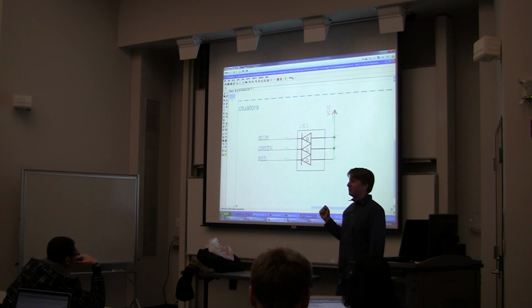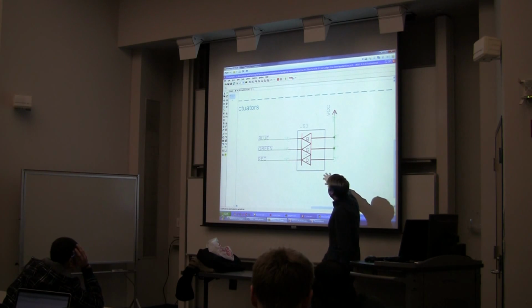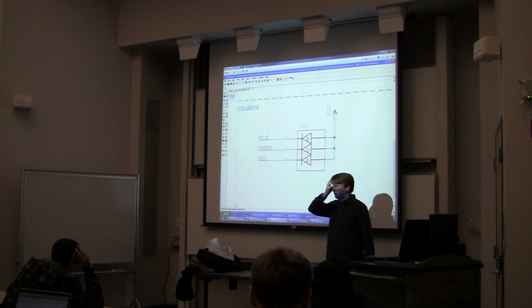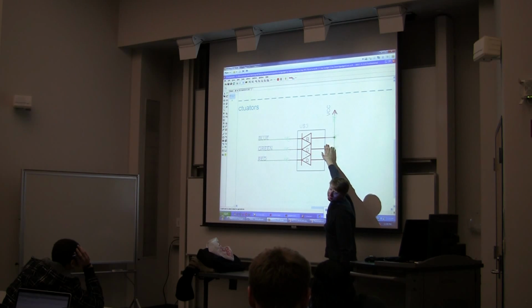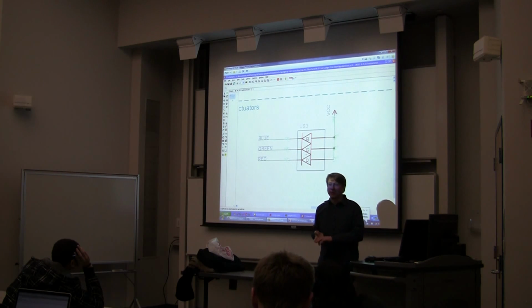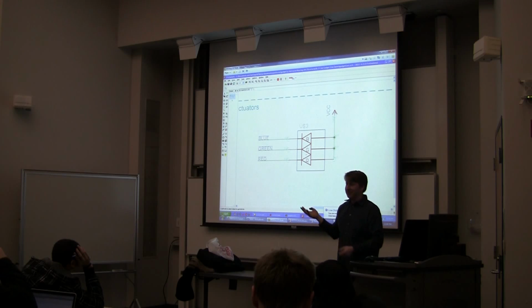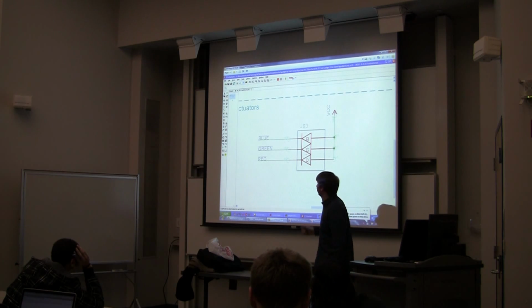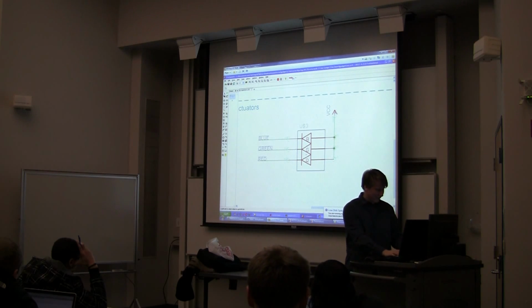Historically, it is always better to sink current. The other detail, when you're buying other LED devices, they almost always are in a common anode configuration where they only give you 4 pins. And you get the low side of each, and then you get one common power pin. So for instance, if I wanted to buy an RGB LED light strip, which is super easy to use and interface to, they're almost always common anode, like this. So some detail. Now I've done all my ERC and I have no more errors.